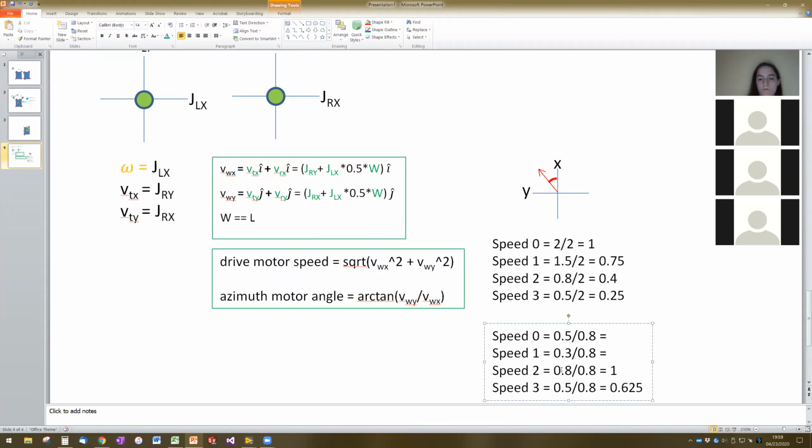So then when you do the normalization, all of a sudden your robot is going faster than what you asked it to. Here you're going slower than what you asked to, but you're going as fast as what's physically possible. Whereas in this scenario, all of a sudden you've made the robot go faster. It's still physically possible, but now it's actually going faster than what you've asked it to. And so you don't really want that behavior either. And so there's a piece of logic in there that Alex put in so that it only does this rescaling if at least one of the requested speeds is larger than 1.